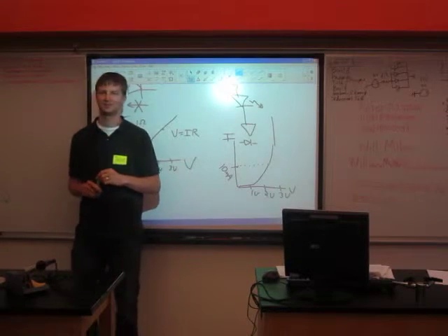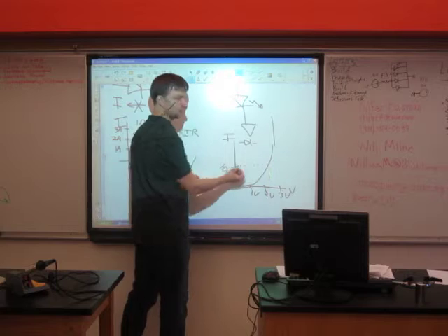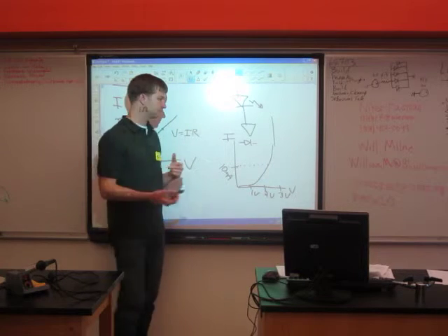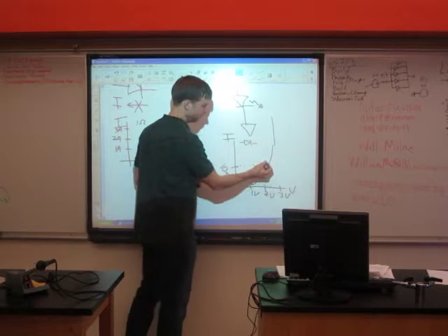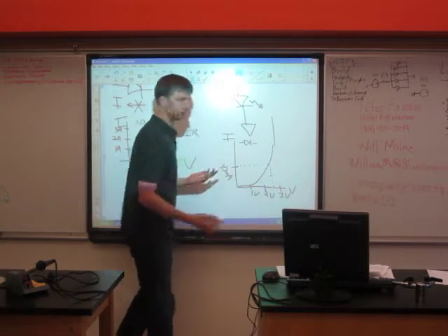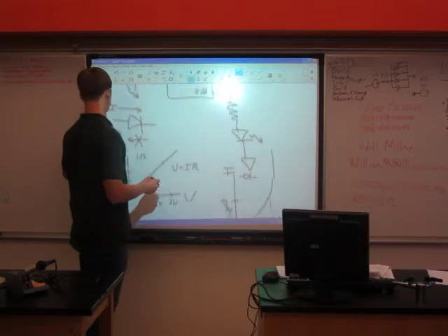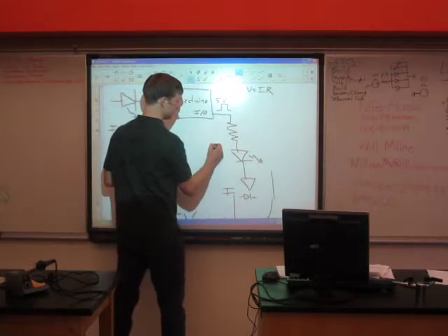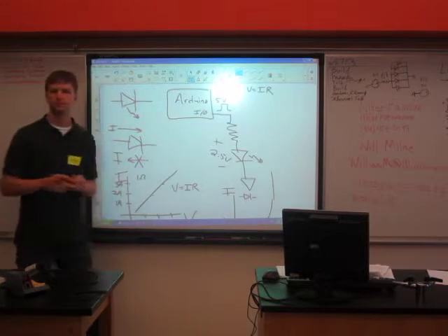Okay. So we're going to take 10 milliamps, and we're going to say this data sheet says this diode likes to light up at 10 milliamps. And then we look at the data sheet, which has this curve on it, and we figure out at 10 milliamps, it likes 2.5 volts. Awesome. So we know that this wants to be 2.5 volts, right?